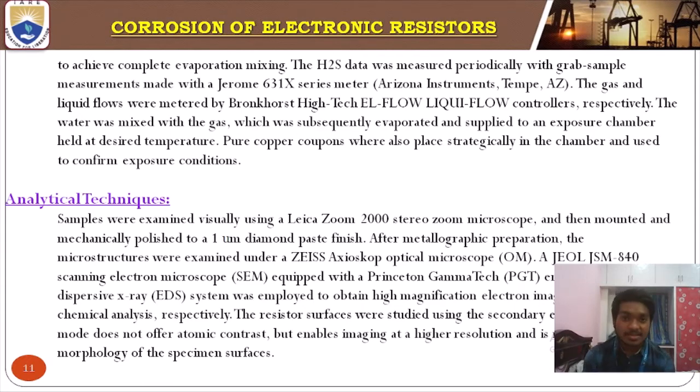Analytical techniques. Samples were examined visually using a Leica Zoom 2000 stereo zoom microscope and then mounted and mechanically polished to a 1 micrometer diamond paste finish.